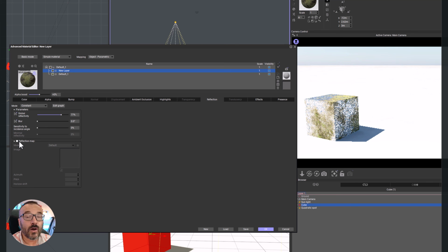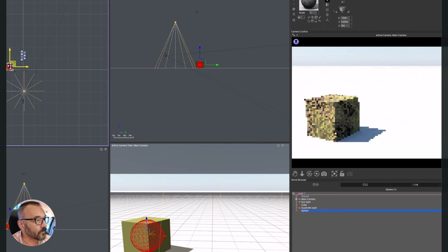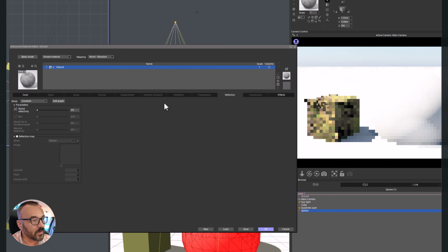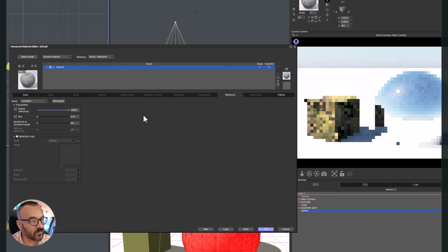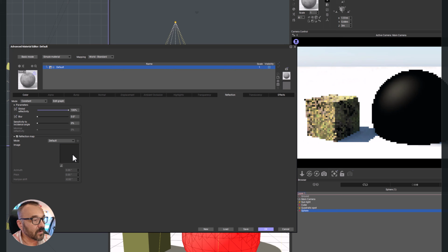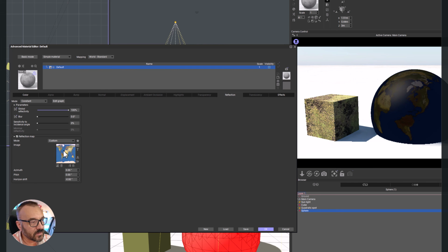We also have the option of a reflection map, which is kind of nice, because if you create an object like a shiny robot, or a sphere in this case. Well, okay, let's do it this way. Let's actually create our sphere. Beautiful, beautiful sphere. And we're going inside and we'll go to reflection. We have 100% reflective. You'll notice it's a boring reflection. What if I don't want to reflect everything that is there? Then I can make my reflection map. I'll go upload it. Let's select the world. And you can see right here we have our reflection map set as a world.